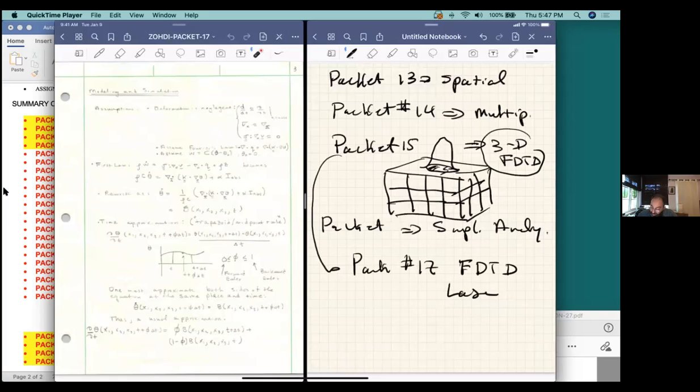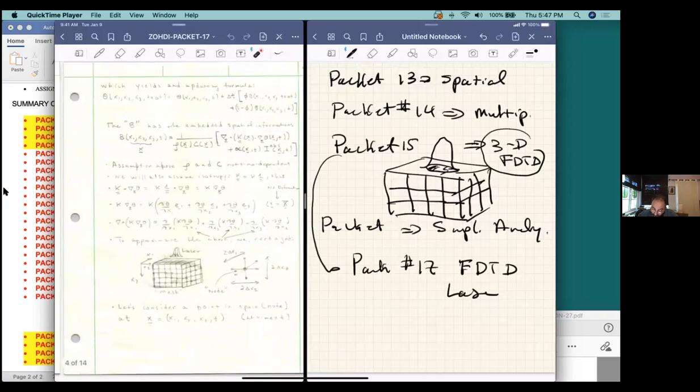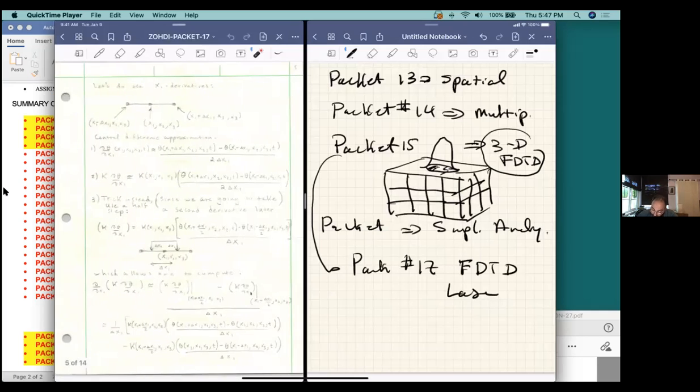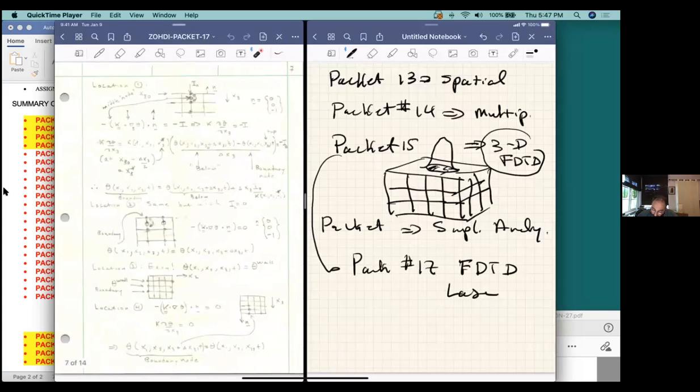And again, the problems are almost always the same broken record. We set up the first law of thermodynamics. We make some approximations. We get it into tractable form. We then apply the boundary conditions onto the surfaces, depending upon what they are. We apply approximations to the derivatives, in this case, of course, in 3 dimensions. And then we set this thing up with all of the boundary conditions.